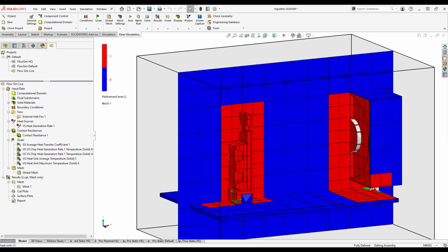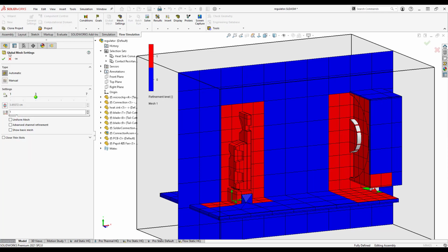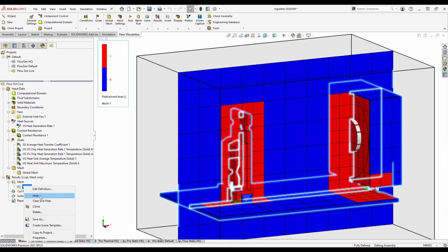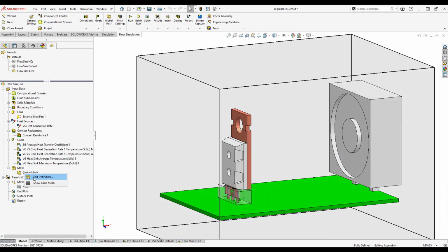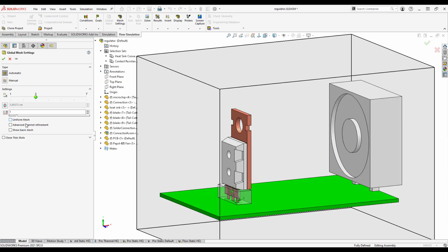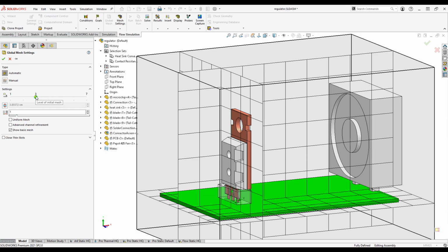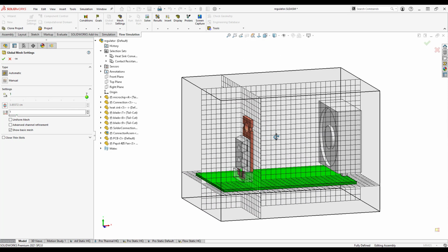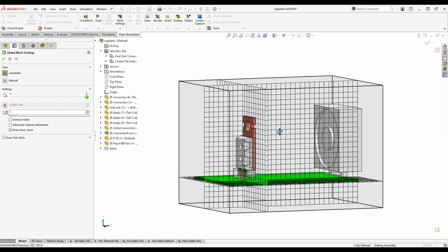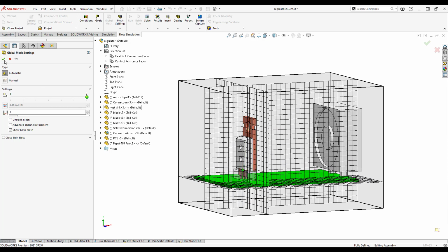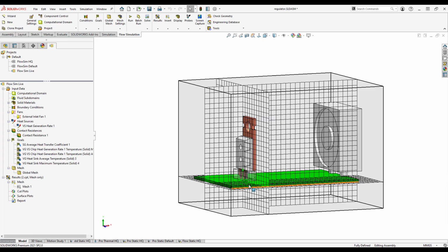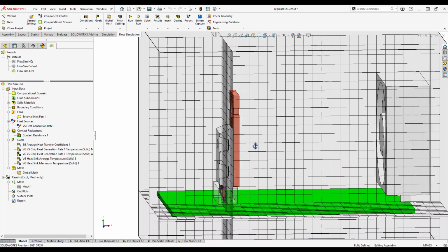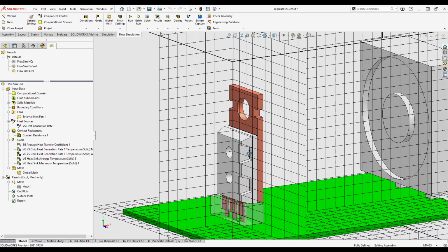So we'll go through that process quickly here. We're going to first go into the global mesh. That's what we just did. And actually, I'm going to hide that plot so it's out of the way while I'm doing this. But show the basic mesh here, and we tested it out that the basic mesh, the starting point, is good enough with just the maximum level at 7 on the automatic type. And then from here, just looking at that basic mesh, we are probably going to need some local refinements too.